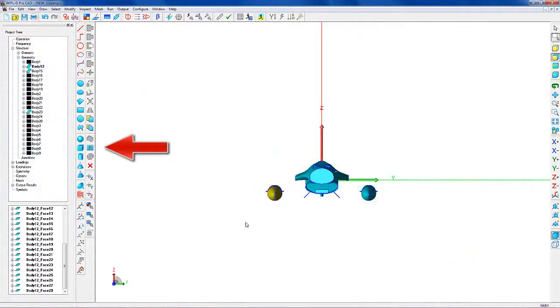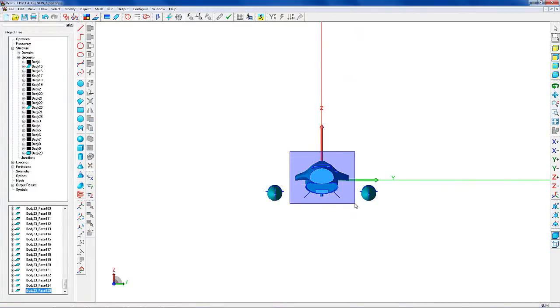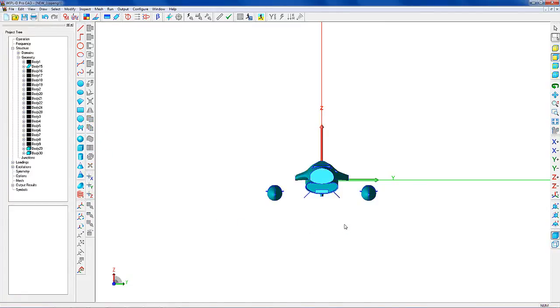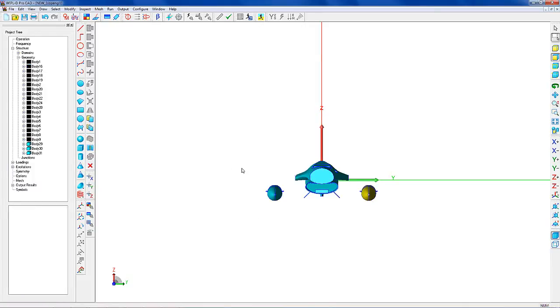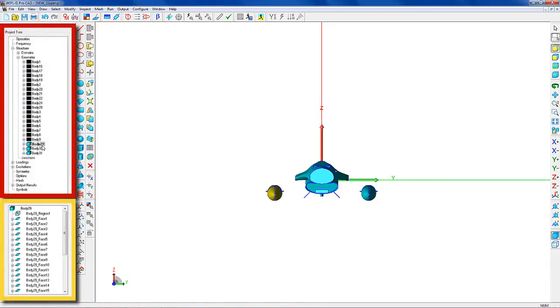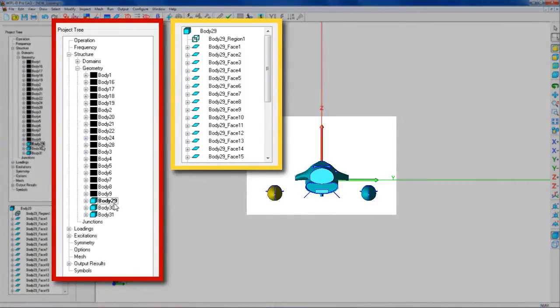Thus, invoke the healing tool named Sew Faces. The process consists of selecting all faces that belong to one unclosed body and applying the feature to them. This operation enables bodies which were not closed to become regularly closed bodies which possess the interior region.